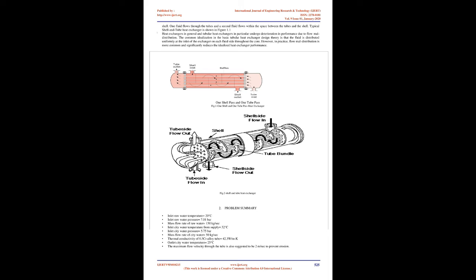The shell and tube heat exchanger is the most common heat exchanger type, therefore the study of its design and analysis is of great importance for conserving energy in heat exchange process. Shell and tube heat exchangers are having special importance in boilers, oil coolers, condensers, preheaters. They are also widely used in process applications as well as the refrigeration and air conditioning industry. The robustness and medium-weighted shape of shell and tube heat exchangers make them well suited for high-pressure operations.